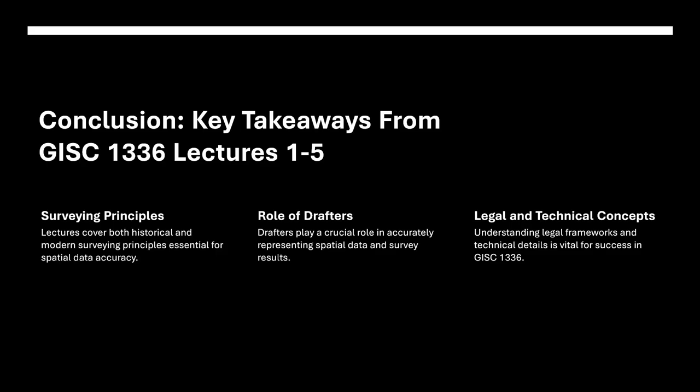All of these cases reinforced the hierarchy of evidence: natural monuments first, artificial monuments second, adjoiners third, courses and distance fourth, area last. They showed us that drafting is not mathematics alone. It is law, history, and evidence intertwined in a digital environment to represent the land.